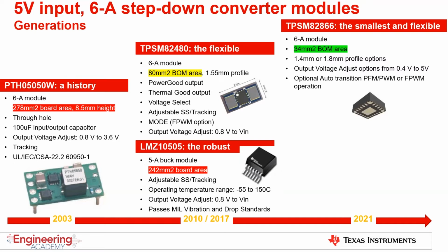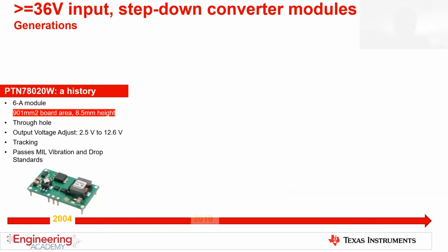Other designs may need an extended operating temperature range to be designed in harsh environments and pass strict vibration and drop tests. Pushing more power in an overall smaller package size requires the power design to be more efficient, but above all, to dissipate heat more efficiently through the PCB or through the package.